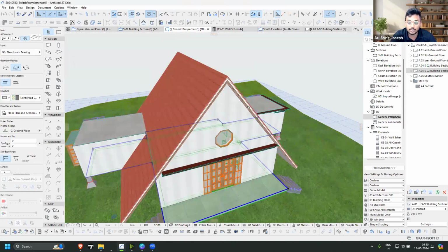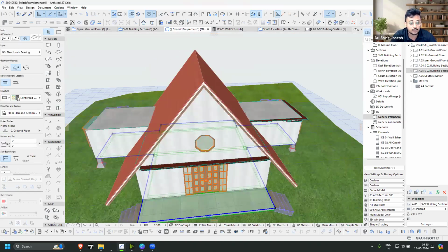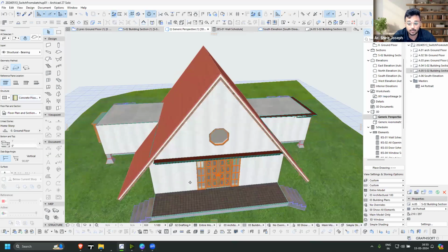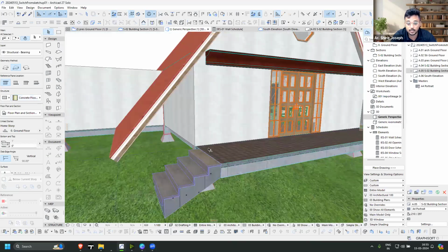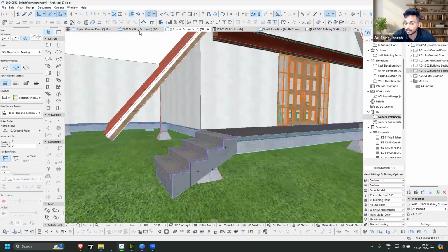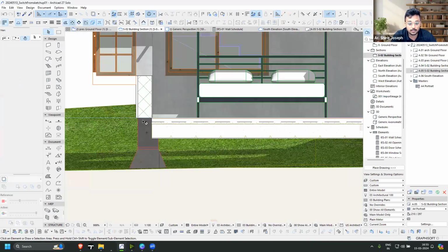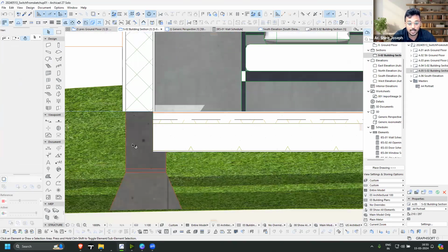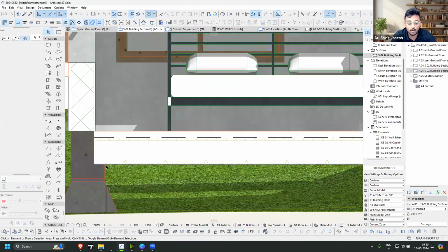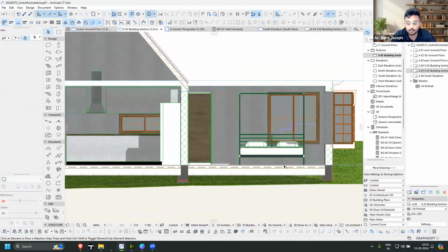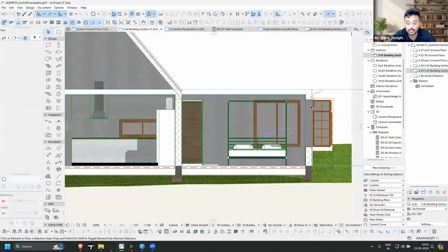accordingly. This floor that we have, again, that also can be updated to a different type of composite, where let us add some insulation to that. And now you will be able to see all the layers here in the plan as well. Now let us explore the same thing in the section, which we created in the previous section. Now you can see the column that is here, the slab that is happening in this, the wall that we created. And also if I go forward and see much more, we will be getting more depth detail here.